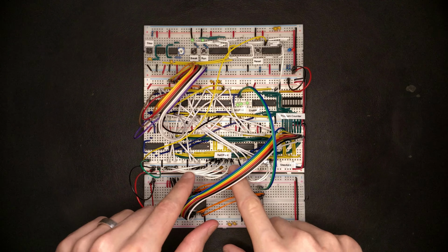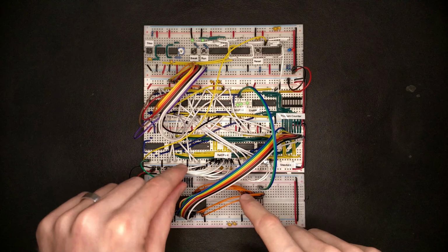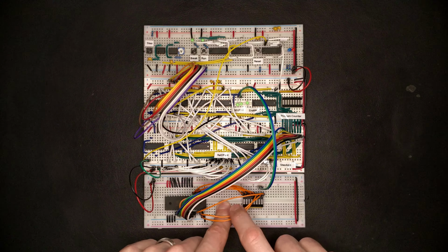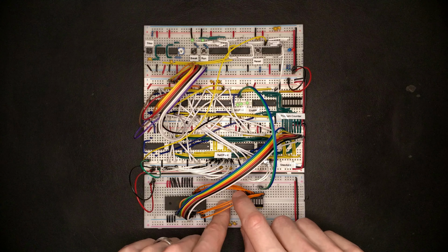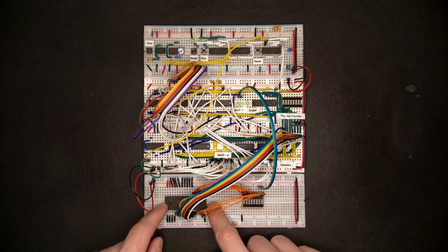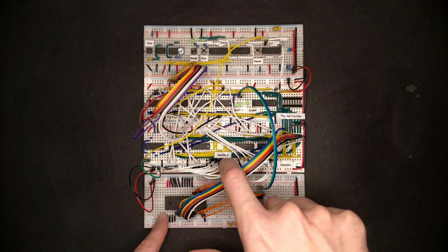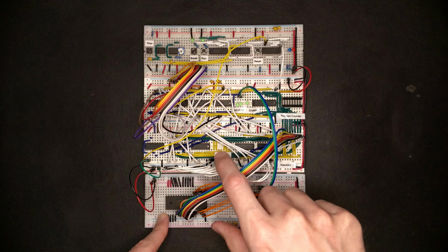Another thing we can do is hook up the relative jump offset of the program counter to a few bits here in the instruction. Let's say maybe the upper 4 bits. And what this allows us to do is, by programming the uppermost 4 bits in memory, we can control what the program counter sees as its relative offset.